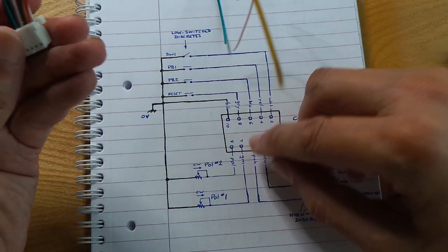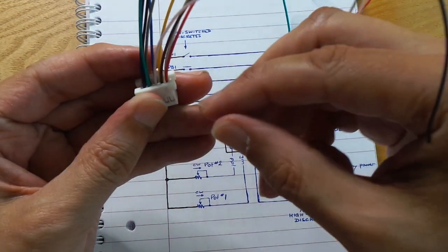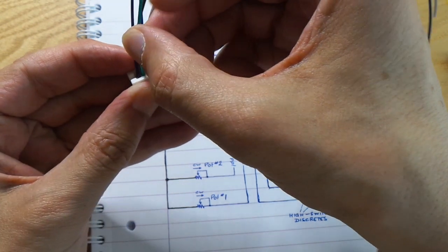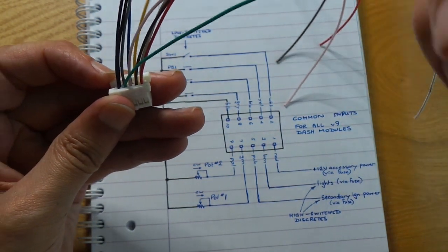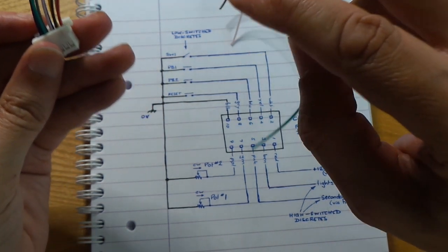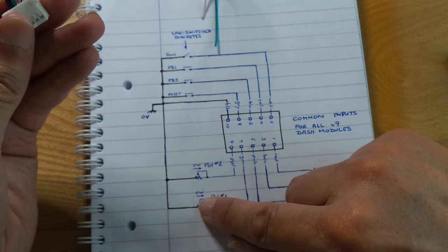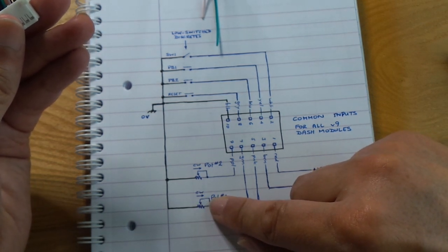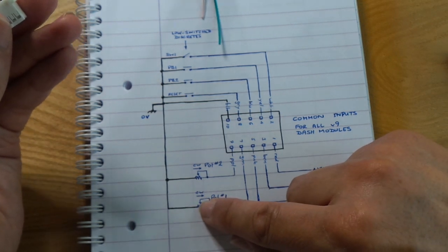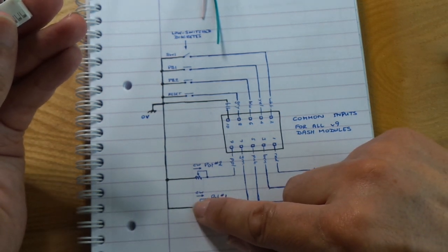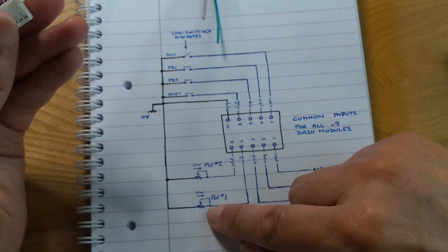Pin 7 is a connection which goes through a potentiometer, enabling us to vary the brightness. That's this green wire here, second from the left on the bottom row, and enables us to connect to a potentiometer, i.e. a variable resistor. And I've put on this diagram here CW pointing to the right. That means if you turn it clockwise, then we're moving the wiper, the middle pin of this potentiometer, to the right. So turning the potentiometer clockwise will increase the resistance, and that will increase the brightness.